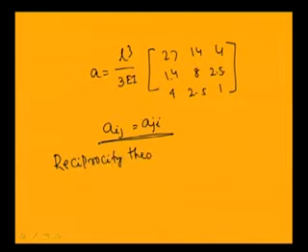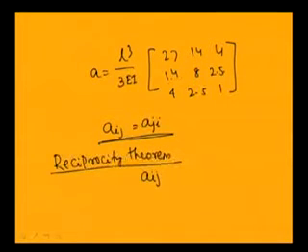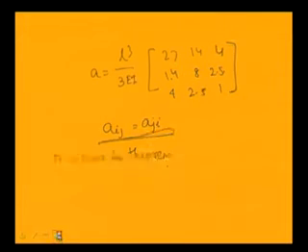For a linear system, which we have considered, you can say that the flexibility influence coefficient Aij equal to Aji. It means displacement at i due to a unit force at j equal to displacement at j due to a unit force at i. So, to prove that, let us take a system.